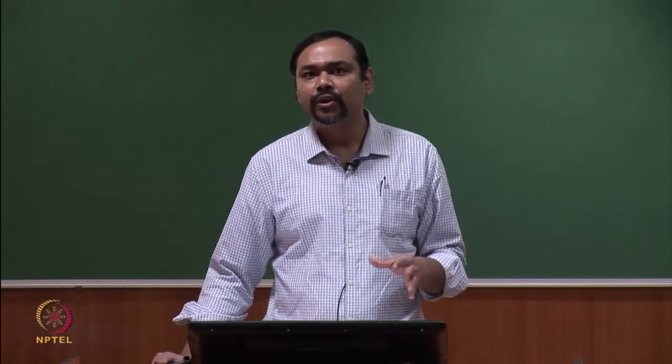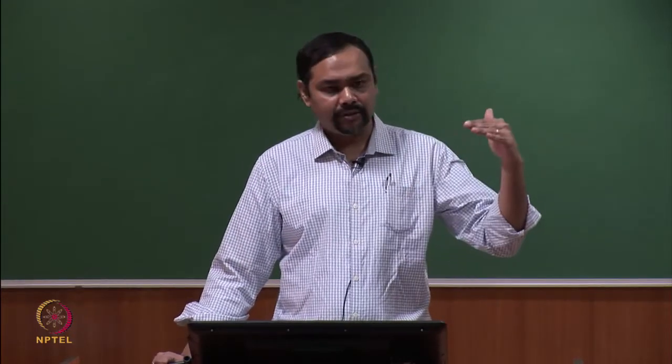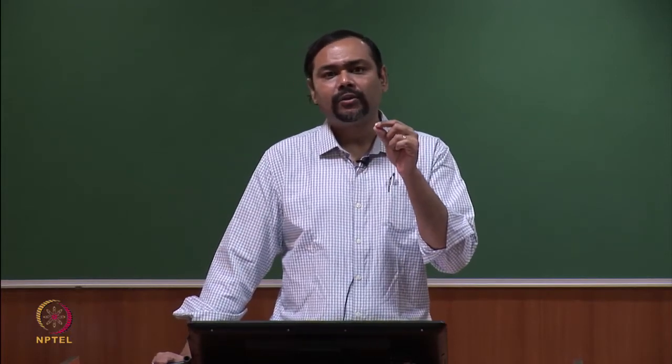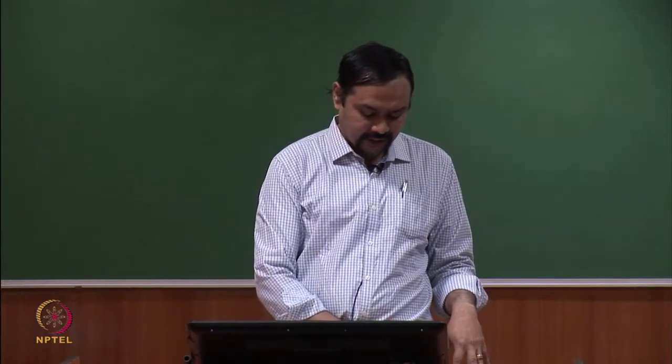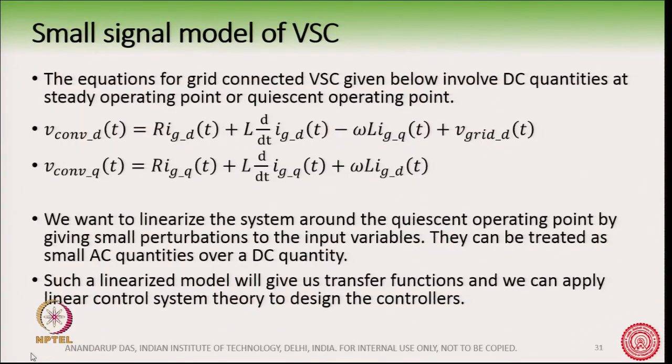Okay. So, what is small signal? Small signal means that you have a DC quantity, you give it a small perturbation, and you see how the transfer function looks in the presence of those small variations. You can see any book on control system and refresh.